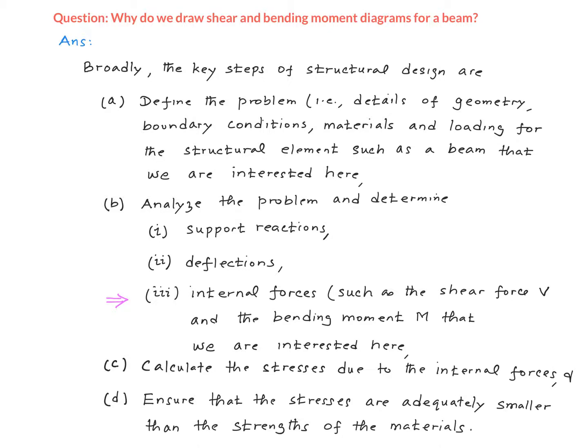the structural element. So you can see the calculation of the internal forces is a major part of this design procedure. So what we do is we go ahead and design the beam for the maximum shear force and the bending moment that occur on the beam.